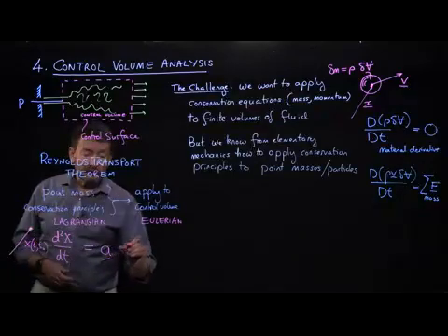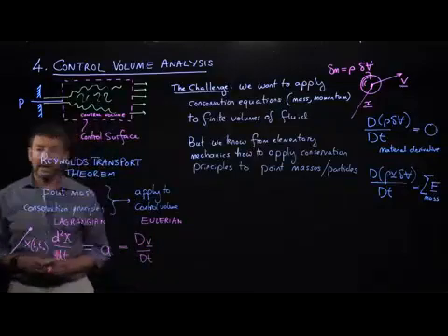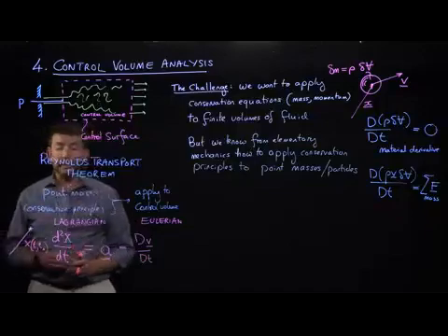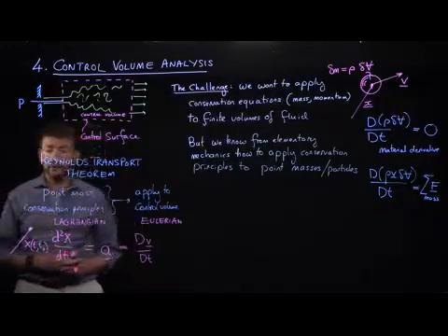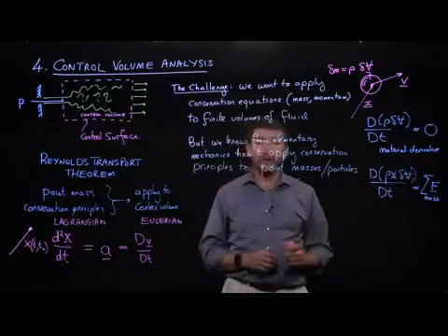And in the Eulerian sense, we can convert that into a material derivative, which recognizes that there were two ways of changing acceleration, one by changes in time and one by changes in space. And so we should expect the material derivative to show up frequently, just as we've shown here.